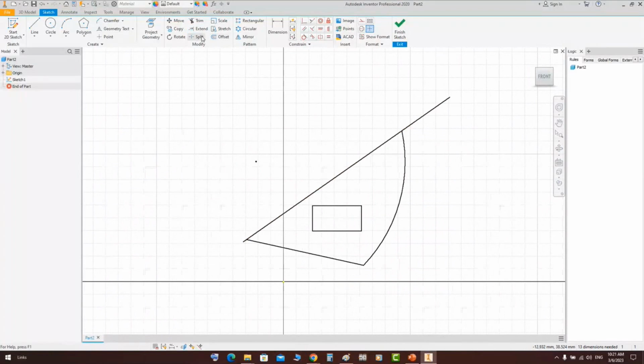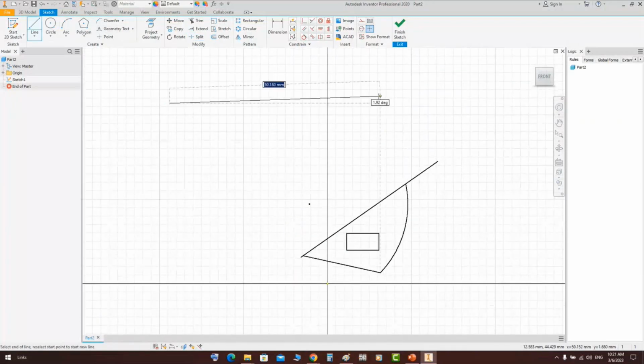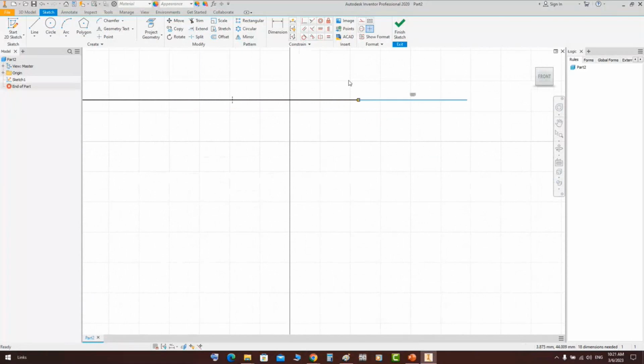Okay. Now the split. If you would like to make a split to align this split tool, for example, if we have a line like that and have some points here, by using the split tool, you will be able to make a cut on that line at the extension of that line here. You will get an intersect point here. So that way, you can make a split. So you will have two lines instead of one line. You make a split at that line.